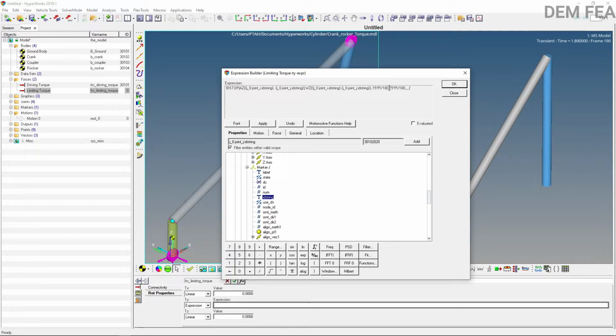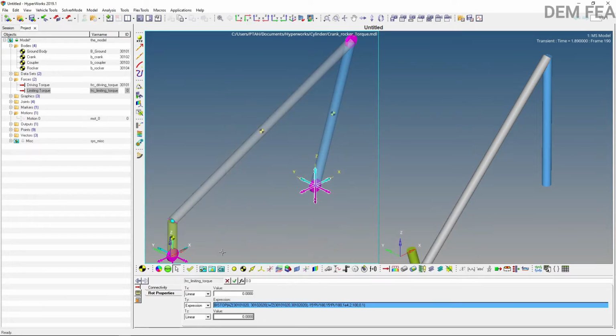Now once we do that, the next thing that we want to define is the stiffness value, which is 1e power 4, 1e4, like that. And then the other value is the deformation characteristics. All these values are already predetermined according to this exercise. And now the next one is the maximum damping coefficient. So you can say it's 100. And then the last one is the penetration value for the damping, at which full damping is complete. This is in millimeters. Now we click evaluated to see if everything is okay. So now everything is okay. As you can see, everything is okay. So now we say okay, like that.